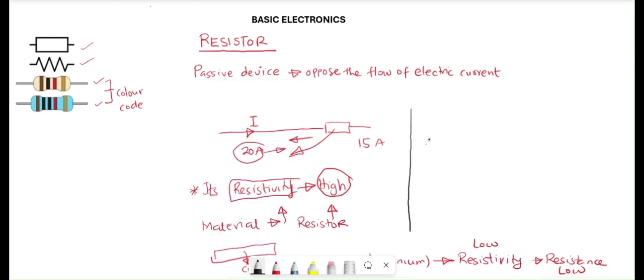Now let's look at the formula for finding the resistance of a device. The resistance that a material will provide is equal to its resistivity multiplied by the length of the material, divided by its cross-sectional area. Just as I indicated, every material has a form of resistivity, and that resistivity is the property that contributes to the resistance.